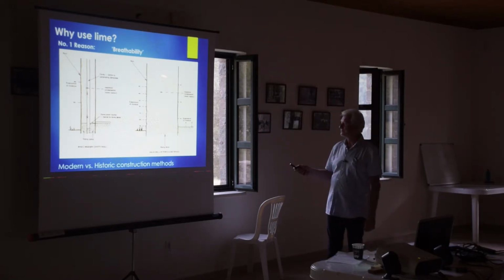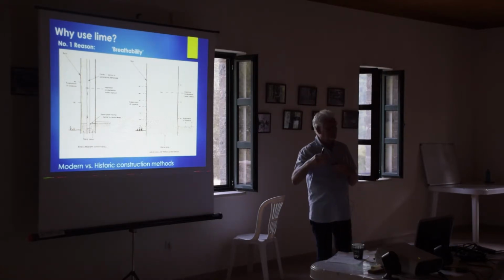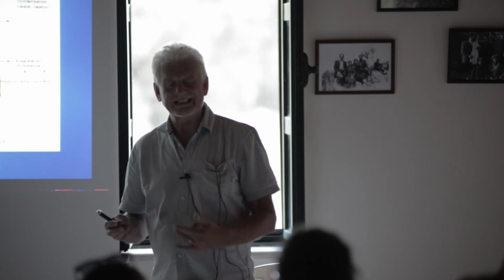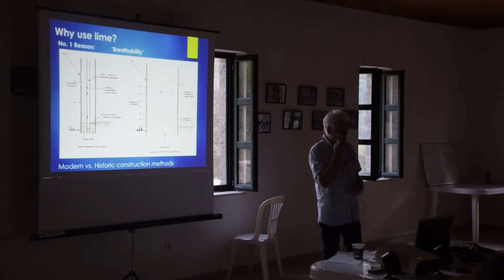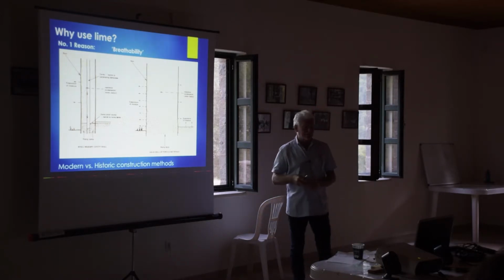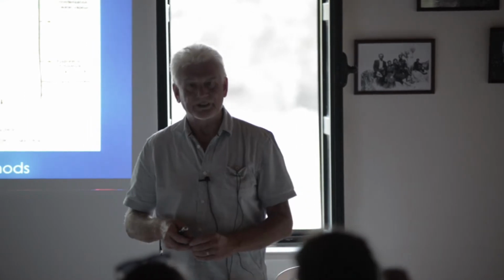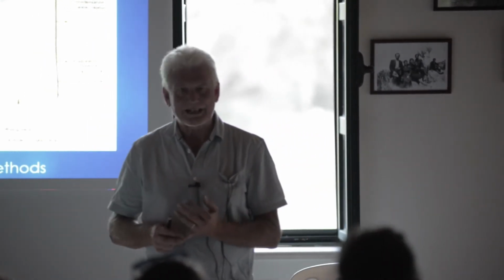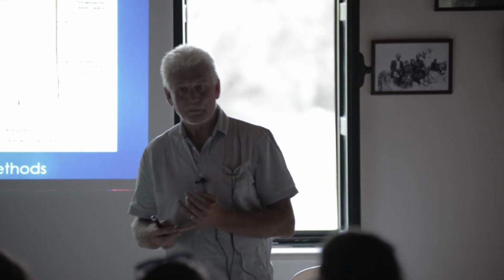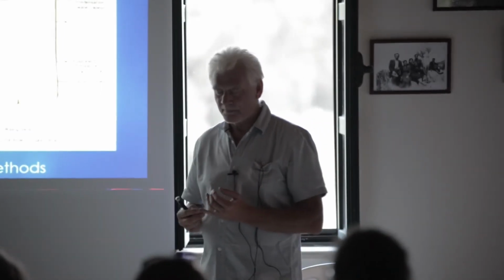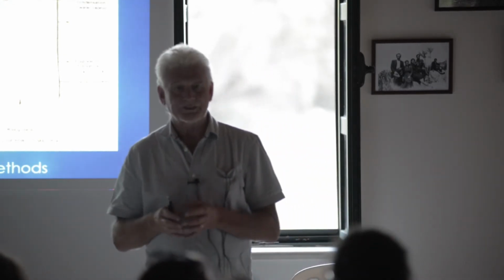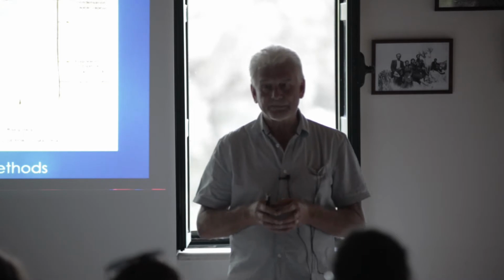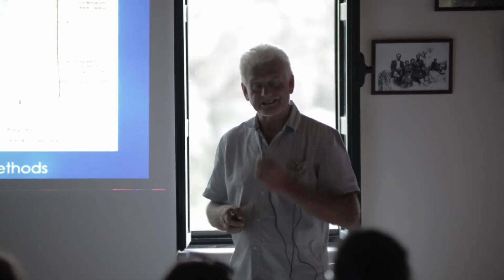These walls are often very thick, solid structures, and that solidity reduces the need for insulation. I can tell you that in Romania, on the older houses now, let's say houses from the 19th century, two terrible things are happening. One is that they're changing all the windows, taking out all the wooden windows and putting in new PVC windows. The first thing that happens is that the interior of the house gets incredible condensation.